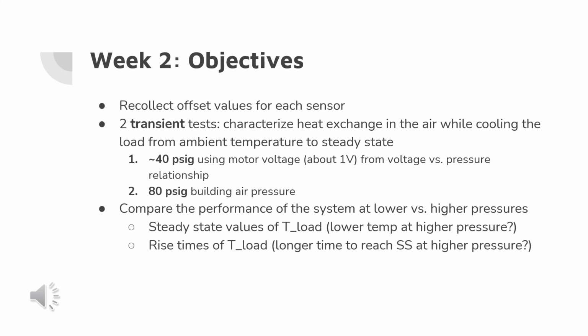We predict that we will see a lower temperature of the load and a longer time to reach steady state for a higher input pressure, but will likely see a less drastic change from the lower pressure due to the decreasing efficiency of the vortex tube's cold outlet at higher pressures.